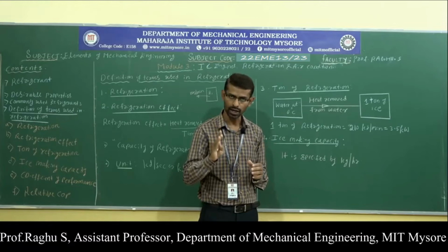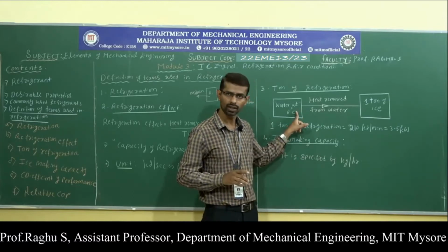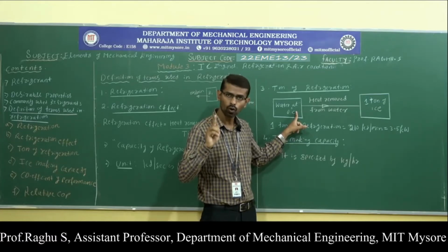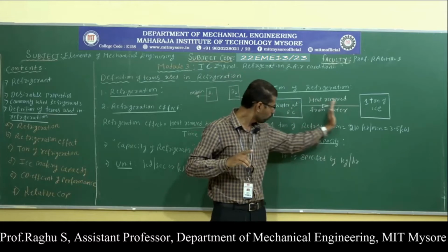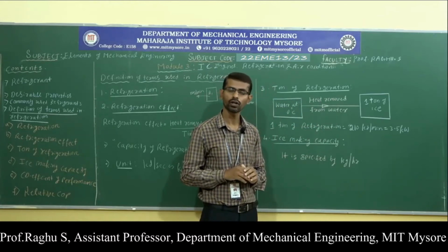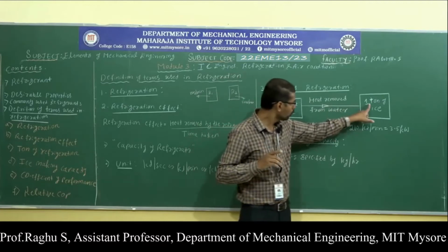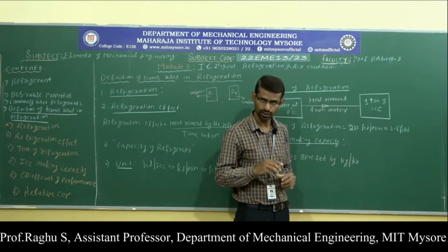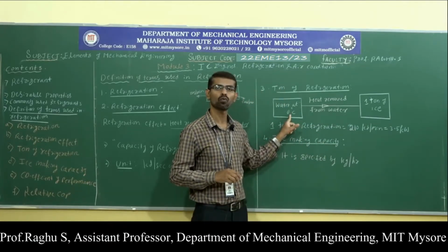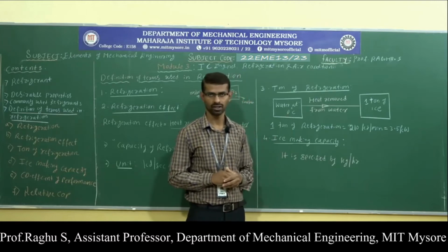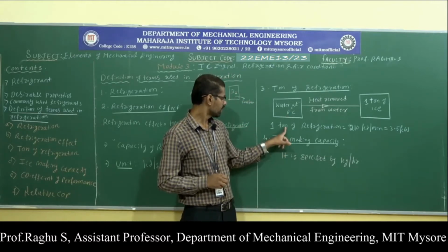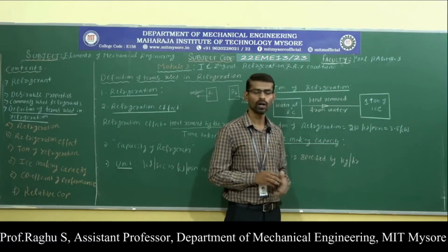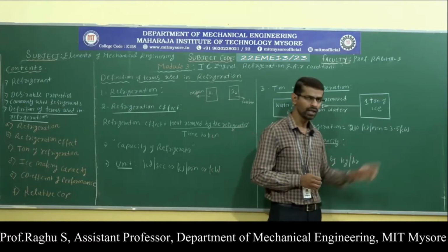See, in order to produce ice, we need to remove heat from the water. So, ton of refrigeration is defined as the amount of heat removed from the water in order to produce 1 ton of ice in 24 hours when the initial temperature of water is at 0 degrees centigrade. So, in SI unit, 1 ton of refrigeration is equal to 210 kilojoule per minute or 3.5 kilowatt.